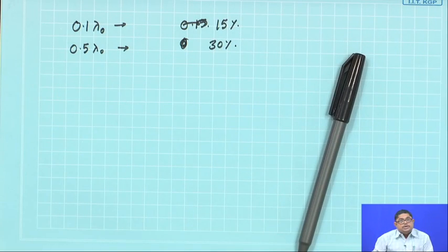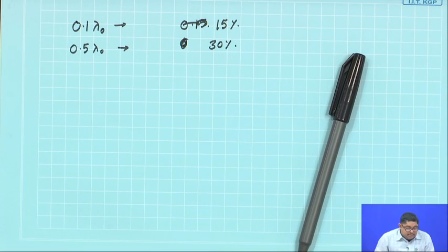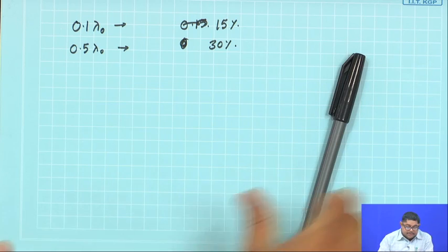So, typically for a Yagi-Uda array, the radiation resistance of the dipole is something like 20 ohm, quite small. Another problem is the frequency band of operation. Usually it does not exceed 2 to 3% because of the critical tuning of the parasitic elements required for optimum results.